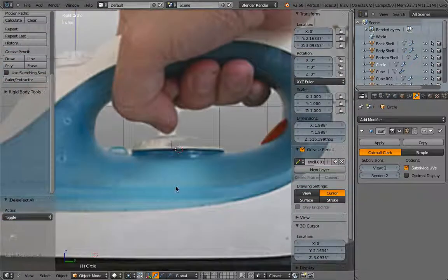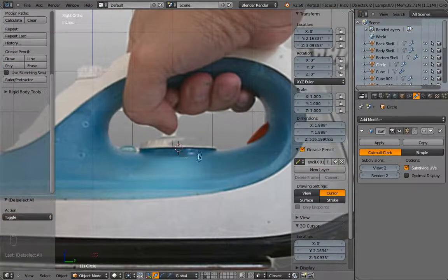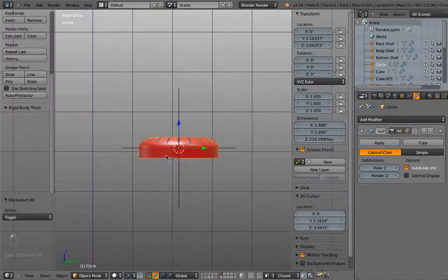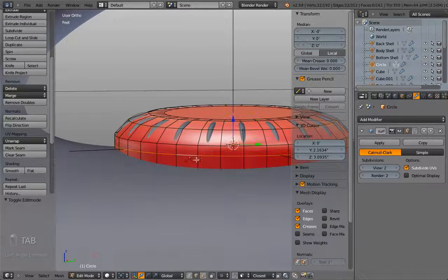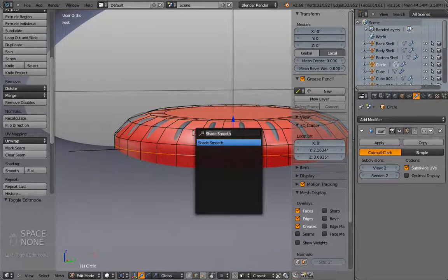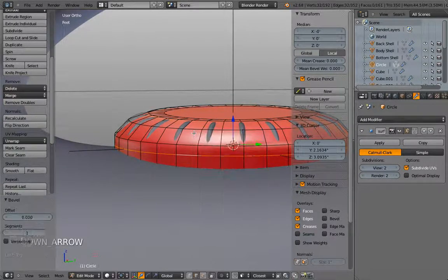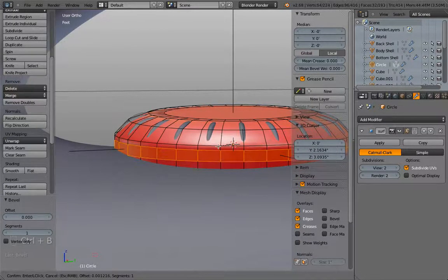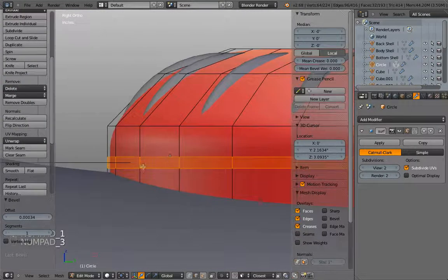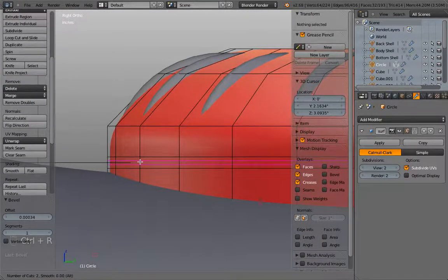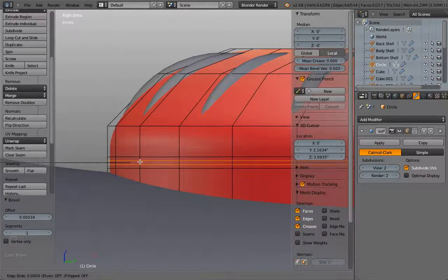Now inside the reference image, you see you have the white dial that rotates and the blue part. So we can do something similar there as well. So maybe here, this rim or this loop cut, I now press Ctrl B or type in spacebar bevel, and I move my mouse slightly, kind of like this. Not too far apart from each other. And then I add another loop cut, 2 cuts on the inside. Press Enter.